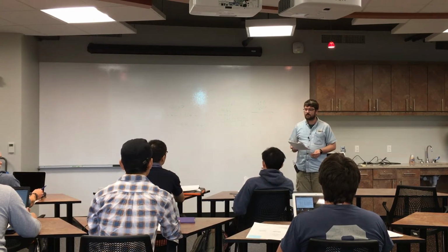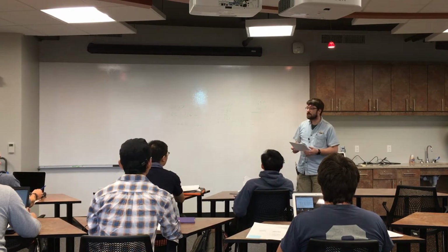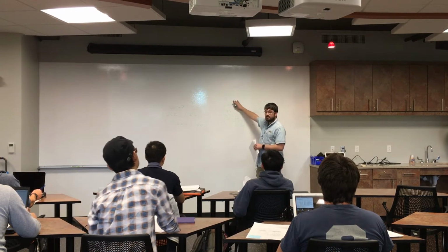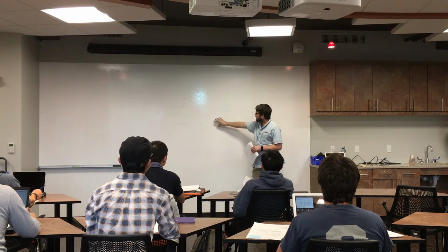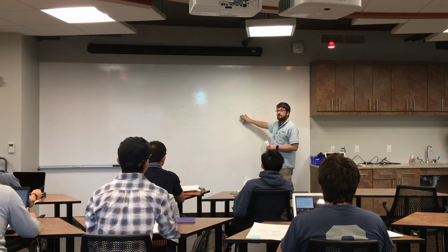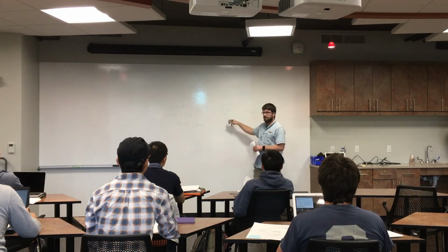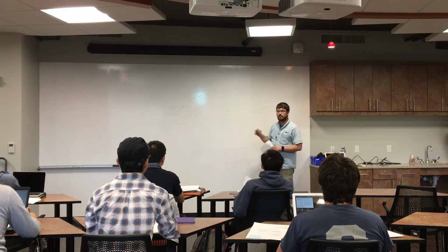So how does that help troubleshooting? So you can say, send the character 0xAA or 0x55, and you would see this on the oscilloscope or on the logic analyzer. You would see this square wave. And that's pretty easy to notice, this nice 50% duty cycle square wave on a screen.